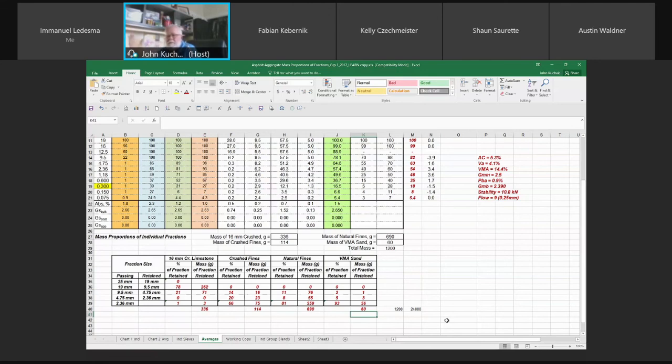You've set your string line out, you've done probably a week's work before you're even ready to pave. So then they're paving a week after compaction's been approved. Why then are you just spraying the grade? You're not doing any more compaction. I only gave you half a mark. Because that's what the slide said.